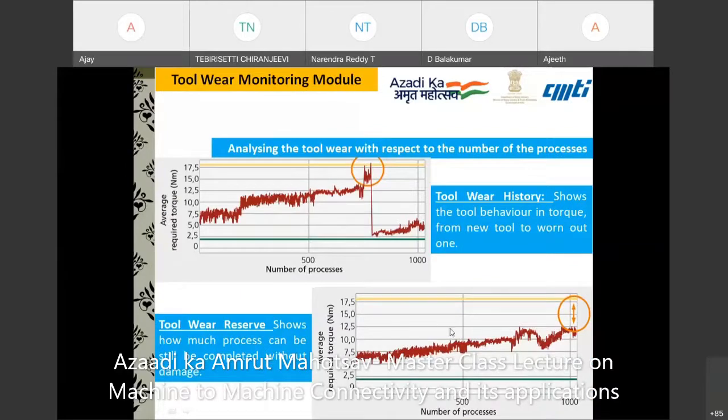And then coming to tool wear monitoring, in most production organizations, again like Sansera kind of organizations, what they generally do is, with the help of their experienced people, they know how long the cutting tool can be used for a particular component. Generally, they will have an understanding like 1,000 components it can produce.